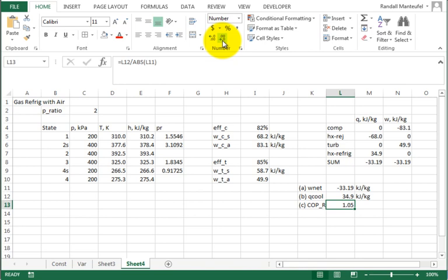Is that a high? No, it's not a high coefficient of performance. Do we see a lot of ideal gas Brayton cycle refrigeration in practice out there? No, we see a lot of vapor compression. You could use this. Why isn't it used more? Probably because of a low coefficient of performance, right? It's low COP. What would be an advantage?